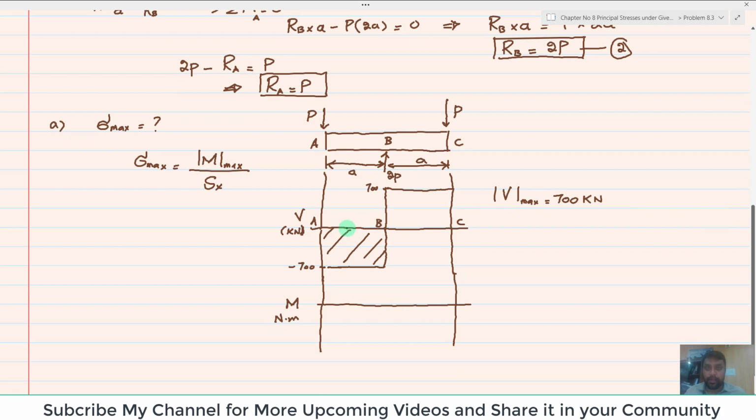2.5. So when you multiply 700 with 2.5, you will get minus 1.75 into 10 raised to power 6. It will be minus 700 multiplied by 2.5. Clear? And this minus 700 is in kilonewton. So when you multiply this, you will get minus 1.75 into 10 raised to power 6 Newton meter. So look, you have to locate minus 1.75. Let this point be minus 1.75 into 10 raised to power 6.